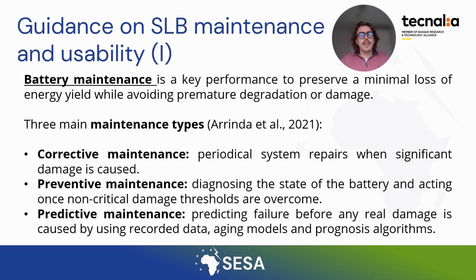So battery maintenance is key to preserve the minimal loss of energy yield of the battery while avoiding damage or repairs for this battery. Three main types of maintenance stand out nowadays. First, we have the corrective maintenance, which basically consists of repairing the battery elements when consistent damage has been caused. Then we have the preventive maintenance, based on diagnosing the state of the battery and acting, but only when a non-critical threshold has been crossed on the system.